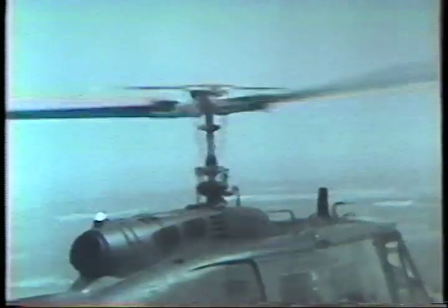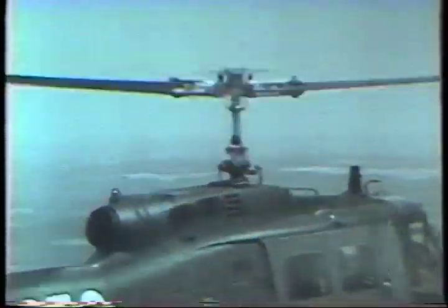This can best be accomplished by positioning your aircraft so that the swash plate assembly of the aircraft you are to hold on is aligned with the horizon. All aircraft within the flight will maintain an interval between helicopters of 2 rotor disc separation, which is measured between the tip path planes. As an aviator, you will fly numerous formations. However, for the purpose of tactical training, this presentation will cover only 6 formations.